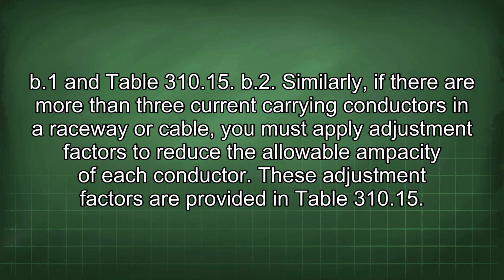Similarly, if there are more than 3 current-carrying conductors in a raceway or cable, you must apply adjustment factors to reduce the allowable ampacity of each conductor.